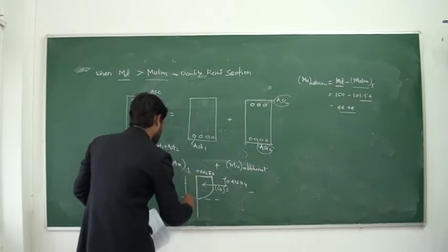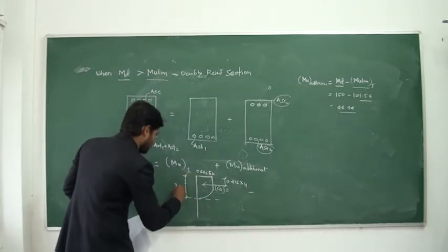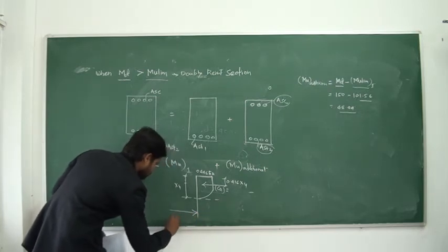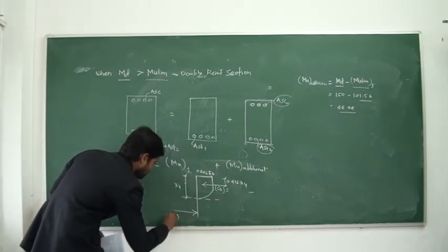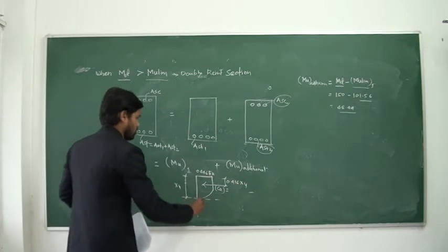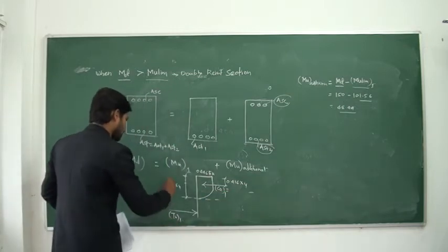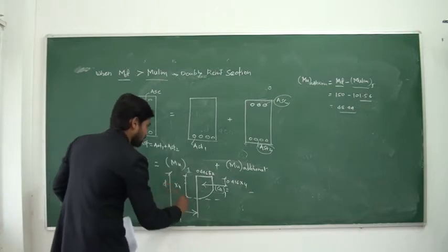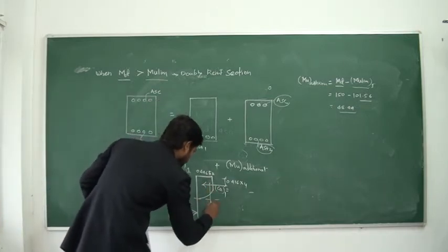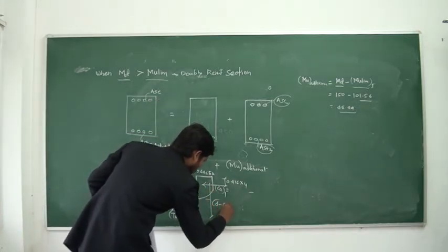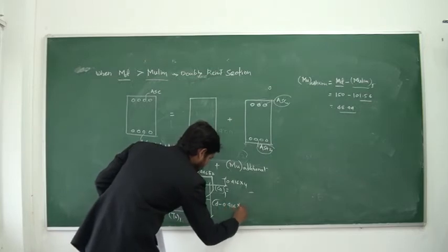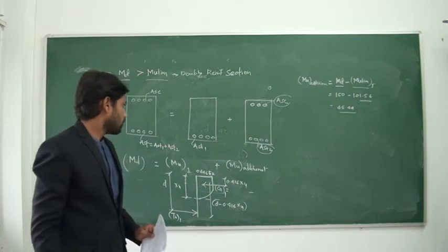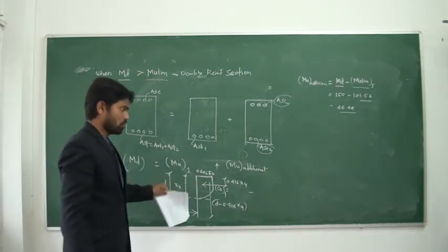This is your depth of neutral axis Xu, and there is the tension at the bottom, which is Tu1. This is the Cu1 compressive force. This is the effective depth d, and the lever arm is d minus 0.416 Xu. We have derived all this in the stress block parameter lecture.